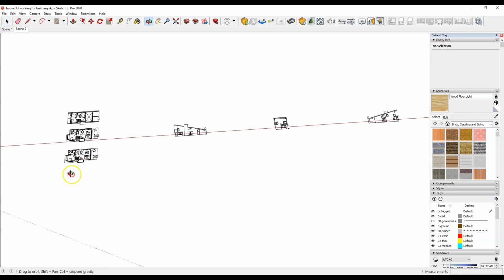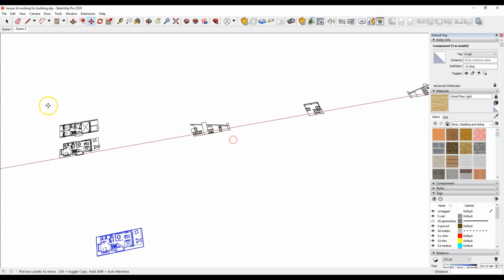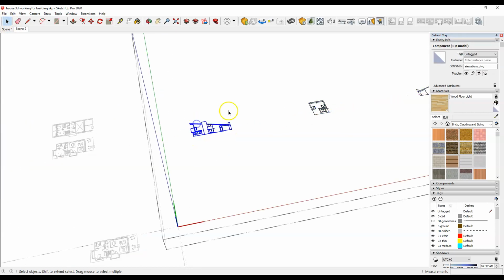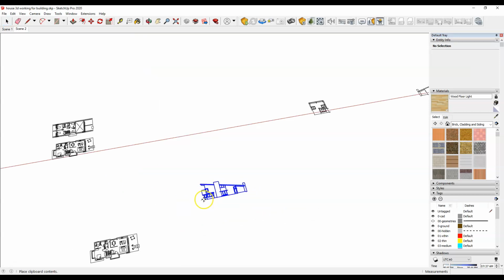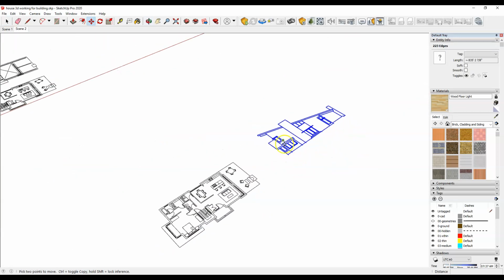So I'm going to show it here, even though I will show it in the specific videos as well. So there's the first floor plan. I'm just going to move it aside. What we need to do is take each of these elevations. I think this is one file. So what I'm going to do is open up the group by double clicking on it, copying one elevation out, and pasting it in. And you're going to rotate these elevations up in the proper orientation.